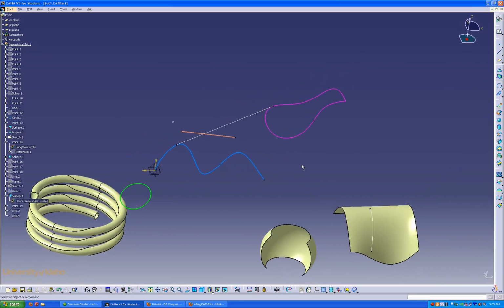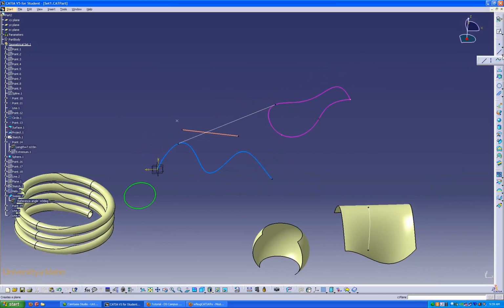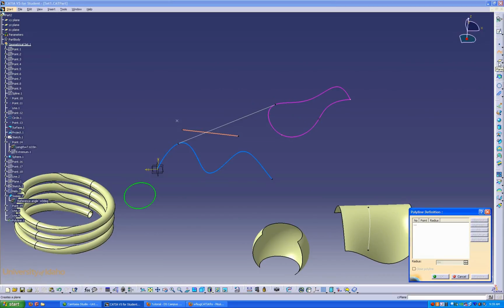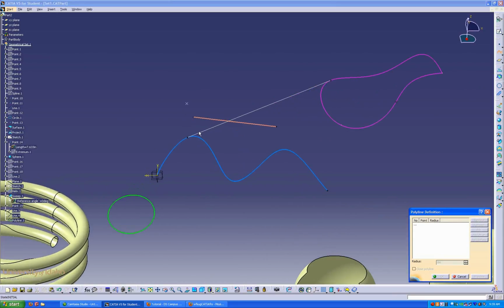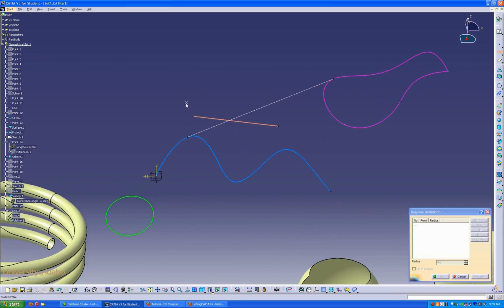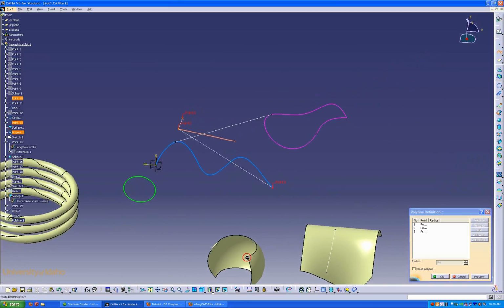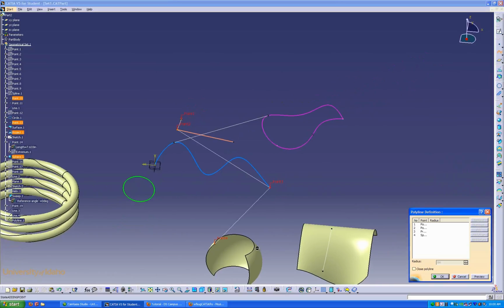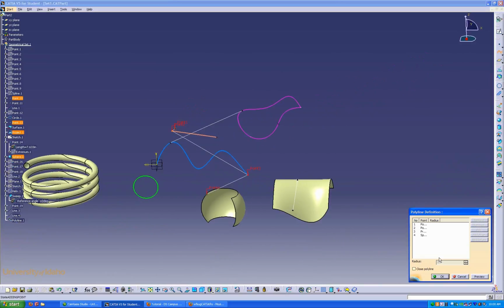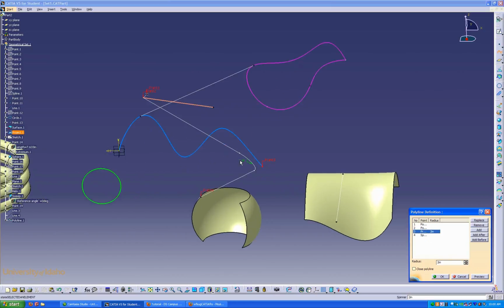Another fun feature you can use in the wireframe is you can make a multi-line. So you simply hit various lines. There we go. And you can make a line there. You can make it go down to here. You can go up over to here now. Put it wherever you want to put it, and then you can click on these and you can change it. So let's say we want 0.3 to have a radius on it. You can see the radius changing.